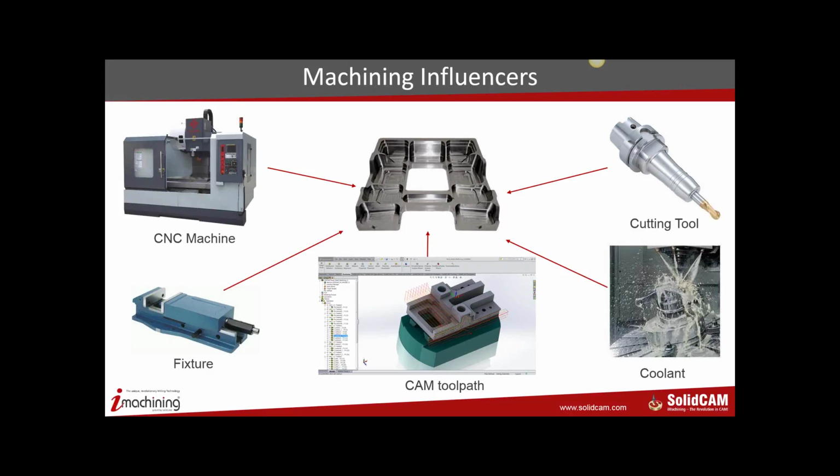Why do I talk about spindle power, the spindle construction? Because you need to have a strong spindle to cut these parts, because number one, they're sticky, number two, they are hard. So you need to have sufficient power on your spindle.